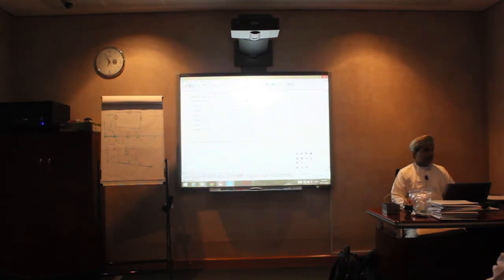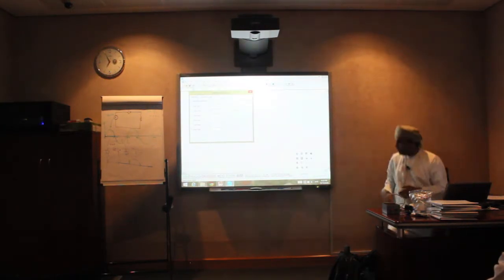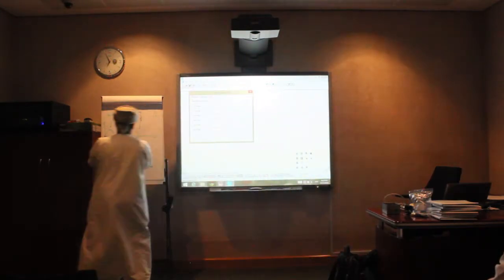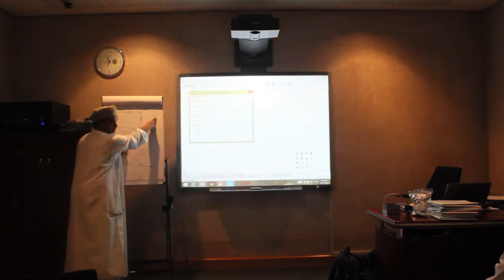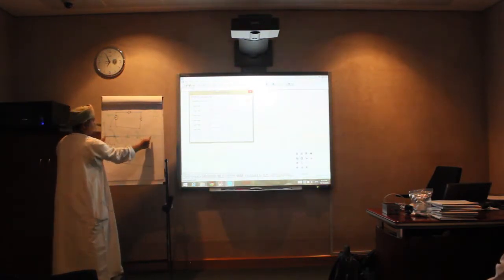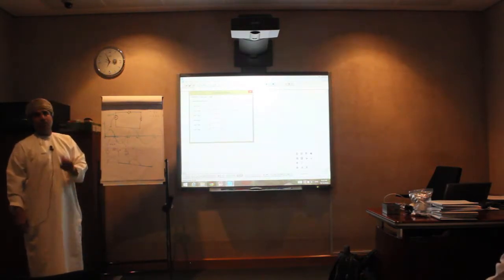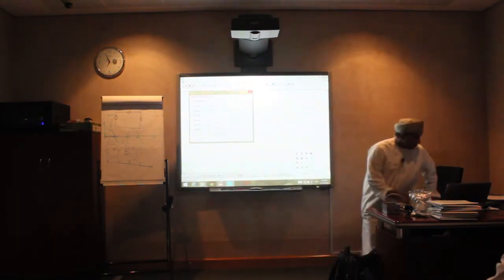This is the control time, but just to define how many cycles I need to run. So this is the time domain. For example, here I can see this is one cycle, right? And the time is 0.02 for 50 Hertz, right? So if I need 2 cycles from here to here, that means I need 0.04 seconds. So I will select 0.04 seconds.